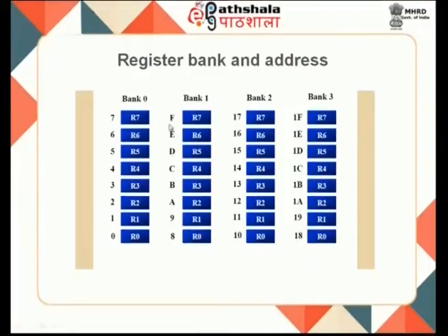So, these values are telling you about the memory addresses, and they have been written in hexadecimal. So, it is given as A, B, C, D, E, F; when decimal 16 is reached, this is converted into 10 in hexadecimal. So, these addresses are written in hexadecimal. Bank 3 is from 18 to 1F. So, I told you 1F to 00 you should not use, it is a reserved space for your register storage.